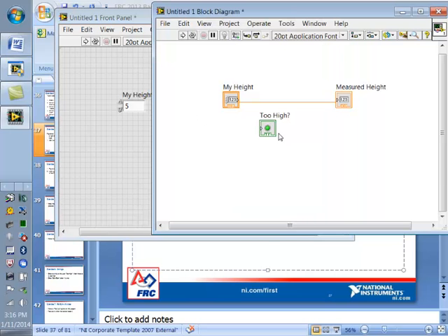On the block diagram, you're going to need to do two things. Actually, three things, but we already know how to do one of them. You're going to have to drop a function that figures out if one thing is greater than another. You're going to have to drop the number that you're going to be greater than. And you're going to have to hook all of that up to the light bulb. The wiring you already know how to do. So how do you find new functions on the block diagram? You right-click. She is now the secretary of right-clicking.